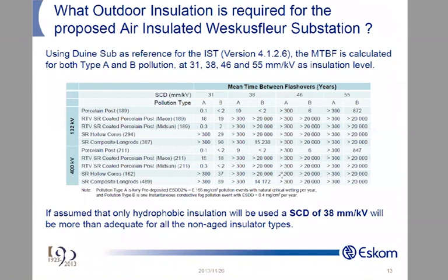Now, I can tell you, which is quite interesting, there's an optimum thickness for the coating as well. Because when you start looking at how this coating works, you've got your porcelain as your base, or your glass as your base. That's a heat sink. The porcelain is a heat sink. So now you put a little blanket over the porcelain. Now the sun is shining, and the energy from the sun is transferred through the silicone slowly into the porcelain, and the porcelain is heating. But now the actual coating is covering like a little blanket. Now remember, it took long for it to get in. It's also taking a long time to get out. So your porcelain insulator now is hotter than a composite next to it.